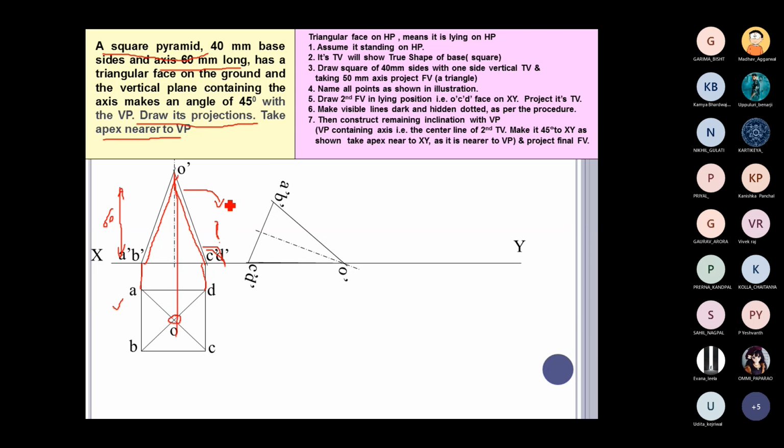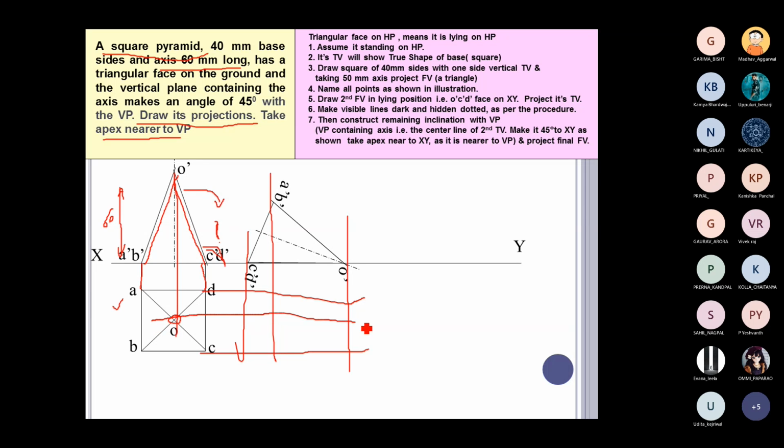Okay, and onwards, we are going to create vertical lines from here to here to here, and then we are going to extend these lines also. Why we are doing this? With the help of this, we can find the common intersection between two points, and with the help of which we can draw our object.